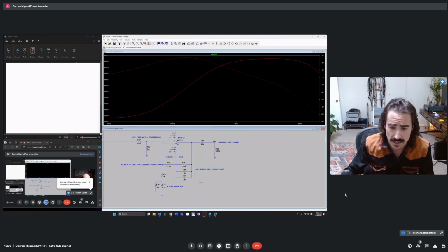But to get an idea of how this works, we're going to start off with applying our 500 hertz pole here. It's actually a zero at 318 microseconds. So if you wanted to imagine the time constant, it's this capacitor to this capacitor here.